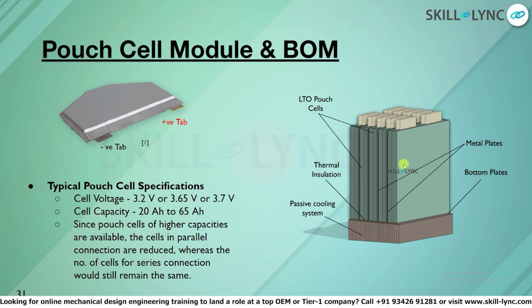you fasten it tightly with a pressure plate, so that all the cells are put together. You're tightening them so that whenever there is expansion and contraction, the cells are not bulging as much, because there's already a pressure acting, so the cells do not tend to expand a lot. So this is something which you need to consider, this complexity. There are a lot of complexities, but you need to do the right selection of design to make it safe.